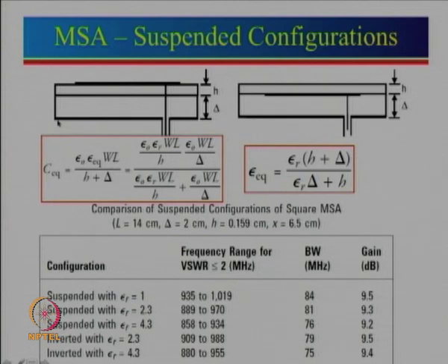And for that metallic plate, again the question is what type of metallic plate? Well, you can take an aluminum metal plate, or you can take copper or brass, or you can get it gold plated, aluminum plated if you have a lot of money to spare, or a very difficult application is required where the tolerances are high as far as extreme temperature variations and other things are concerned. Maybe you need to reduce the conductor losses.